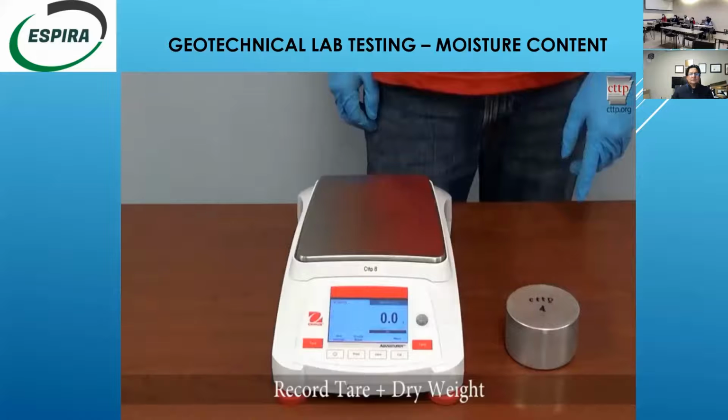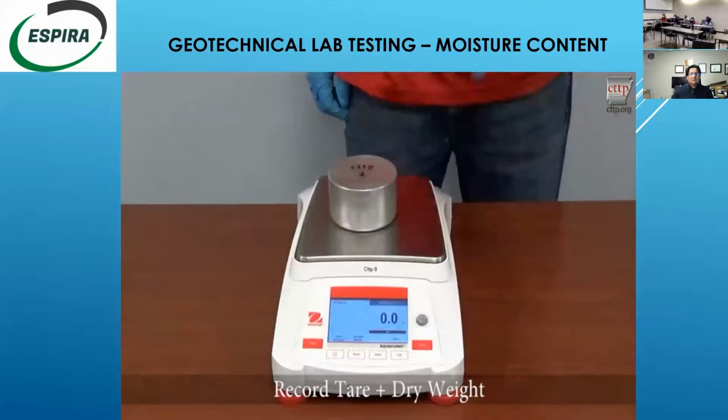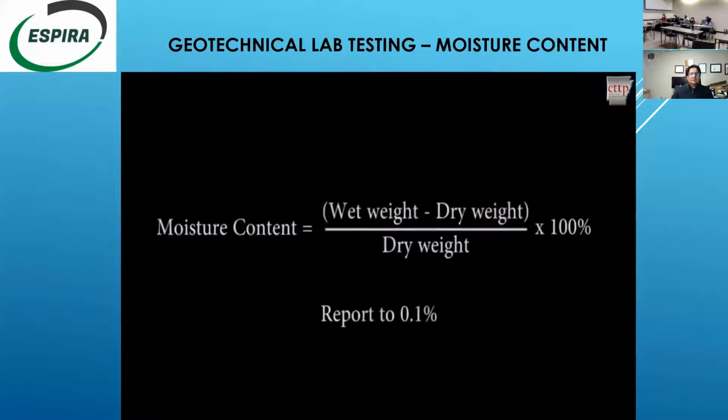Immediately place the lid on top of the container to prevent the sample from absorbing atmospheric moisture. Allow the sample to cool to room temperature. Zero the scale and place the cooled sample container on the scale platform. Record the tare plus dry weight of the sample.